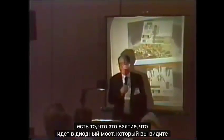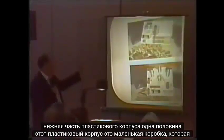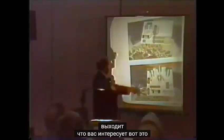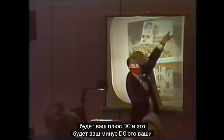Well, basically what's happening there is that this is the offtake that goes into the diode bridge that you see there. That diode bridge is built on the underside of a plastic case. One half of that plastic case, it's a little box that you build electronic projects in. And coming out, what you're interested in here, this is going to be your plus DC, and this is going to be your minus DC.